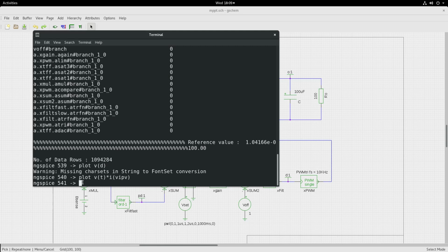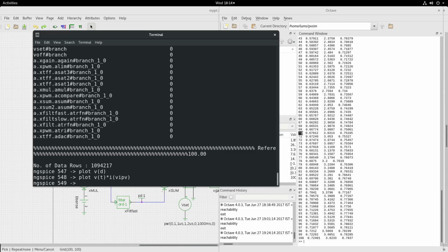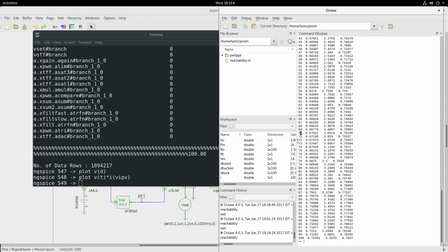What we shall now do is change the value of R0 from 100 to some other value. Let us choose now R0 of 70. So for R0 of 70, the corresponding duty cycle is 0.75, which will work out to be 0.75 into 2 minus 1, around 0.5 will be the value of the voltage input to the PWM carrier.